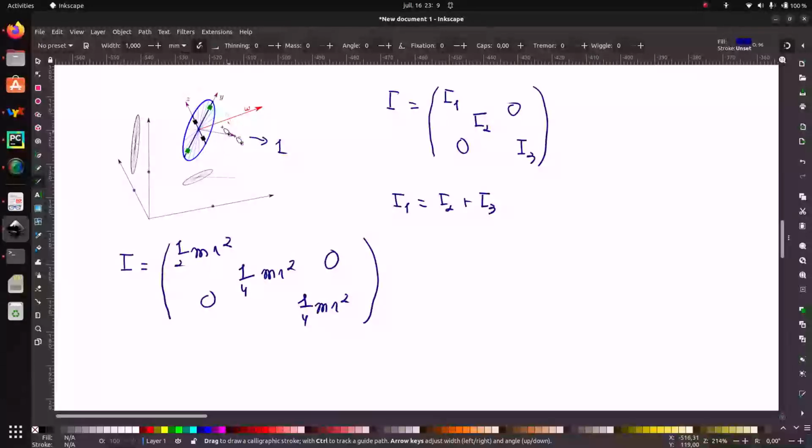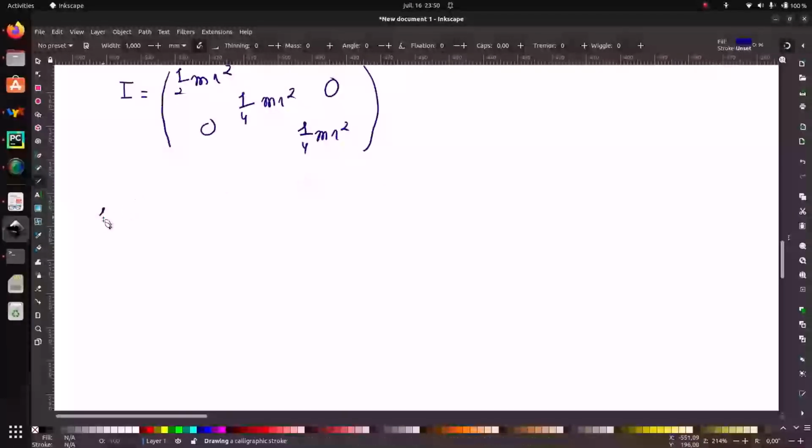So as shown by this picture, the disk is able to spin around an axis, and the axis is named omega. When omega is expressed in the world frame, I will write omega. If it is expressed in the body frame, I will write it omega r. So from this, the question is to find the state equation. For this, I will assume that the orientation is given by the matrix R.